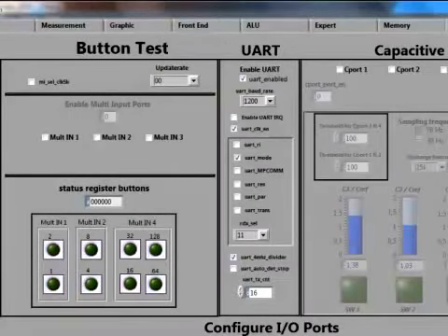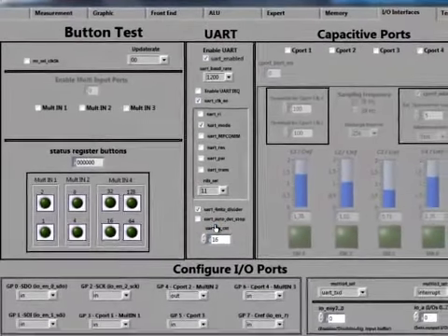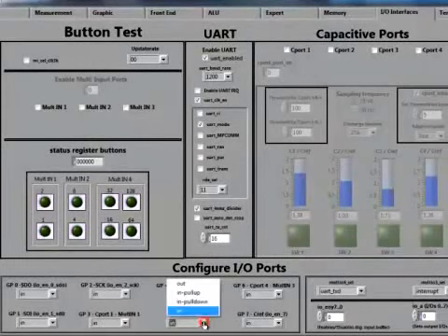To receive using the UART, the same configurations as for transmit are valid. Additionally, the GPIO pin which has to be used as receive input has to be selected in this option here. On the evaluation board, reception only through GPIO 5 is possible. Hence, set this option to 3. Then configure the GPIO 5 as an input so that bytes on GPIO 5 can be received in the chip.